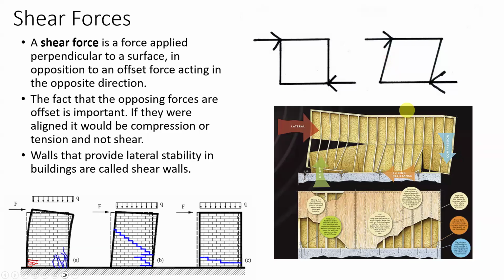Have any of you bought a cheap bookcase at Menards or Home Depot or something, and it's basically particle board, and they're kind of notched together with each other, and then you push on them and the whole thing tips over like a house of cards. But then they give you this tiny little sheet of cardboard or particle board or something, and you nail that into the back. That acts as a shear panel, and it keeps it from racking and tipping over.